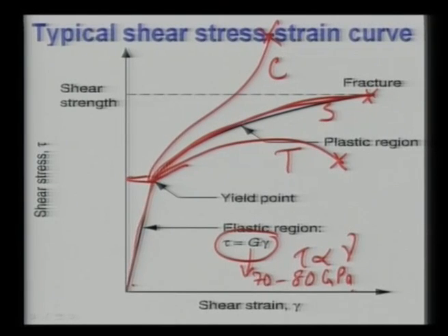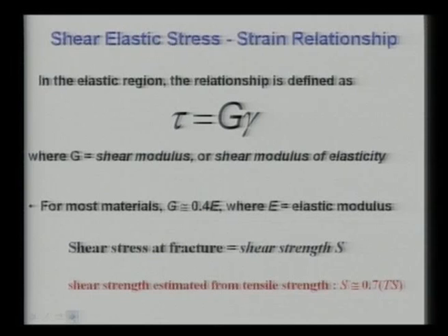In shear stress again it goes in a non-linear manner, but in the tension case it goes through necking, and this necking does not occur in the case of shear and compression. That is why under tension force you have a completely different type of behavior compared to compression. As I said, tau equals G gamma up to the yield limit.